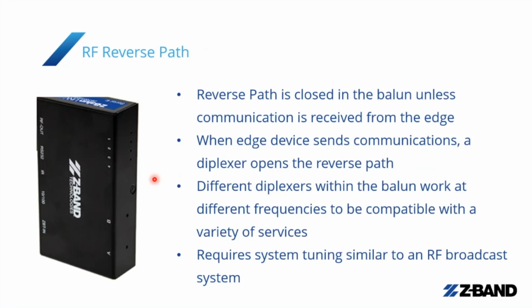And that same concept applies when we're talking about cable service provider set-top boxes. Now, the big trick with cable service provider set-top boxes is it used to be pretty standard. Cable TV was 54 to 860 megahertz. Everything below 54 was T-channels. So any set-top box communications from your cable service provider lived underneath 54 megahertz in the frequency spectrum. Anyway, now with DOCSIS 3.1, and as we've moved forward, that reverse path communications has moved up. And now the communications path all the way back to the service provider goes as high as 225 or 250 megahertz. I think it's 225 off the top of my head.